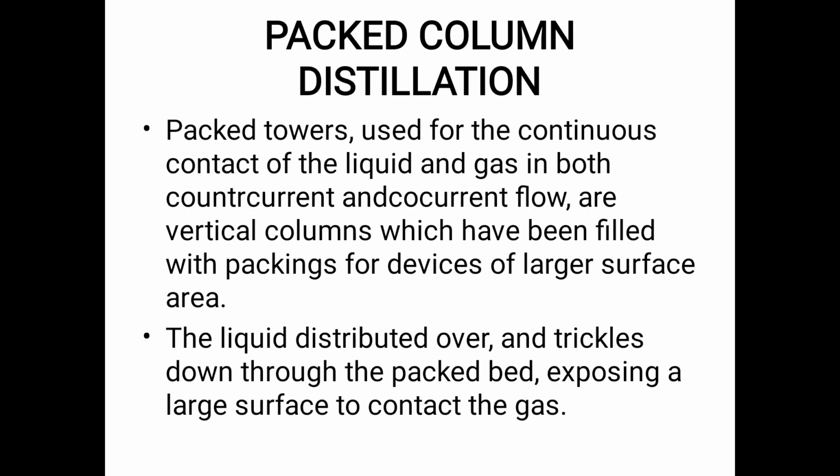The liquid is distributed over and trickles down through the packed bed, exposing a large surface to contact the gas. In a packed tower, the contact between gas and liquid is greater, so the mass transfer rate is increased. The purity of the product may be increased compared to the remaining distillation columns.